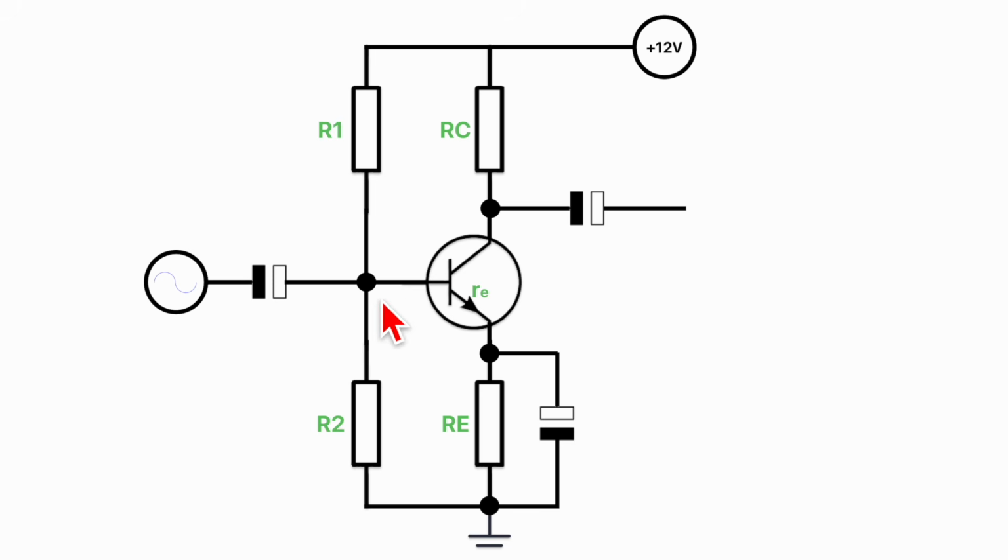But it will be a faithful copy of what we see here, but just bigger by beta times, by the gain times. And so essentially what we're doing is we've got DC current flowing through here, and that's being amplified and flowing through here. So all we're doing really is we're hitching a ride. We're getting our signal, as it were, thumbed a lift, our AC audio signal, riding on the back of this DC current that's going through anyway. And because the DC current is being amplified as well, so is the AC signal.